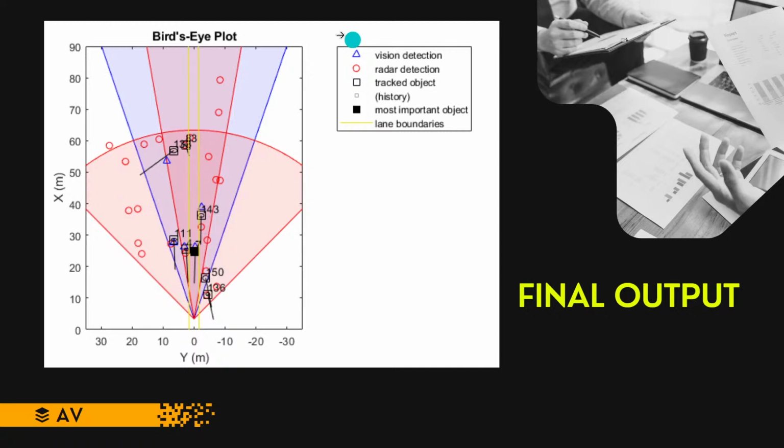So next one is the small circle. Red small circle is the radar detection. So these are all the radar sensors on the car. They can detect objects by bouncing signals off them. So next one, we are keeping track of some of these objects over time. We know where they are and how fast they are moving and even how certain we are about their position. So we also give them labels so we can tell exactly.